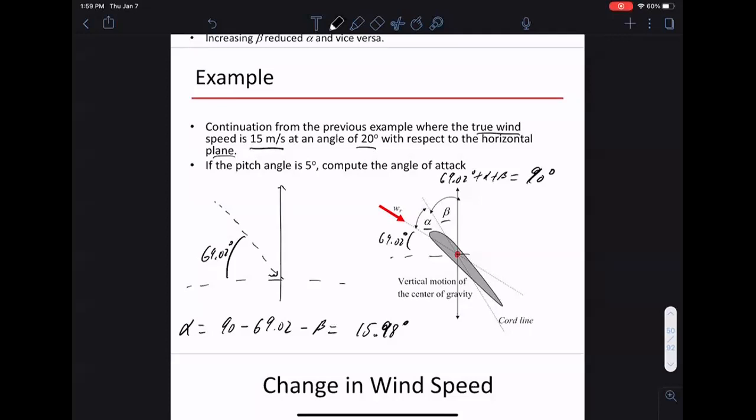In practice, let's say you have a turbine and want to track a constant power output. Then if the direction of wind changes, or the speed or the angle changes, then power output will change, right? But what you can do is slowly change beta to try to adjust your power output to go back to the nominal output. But normally we never say, given this power I want, compute beta. It's more of a tracking problem.